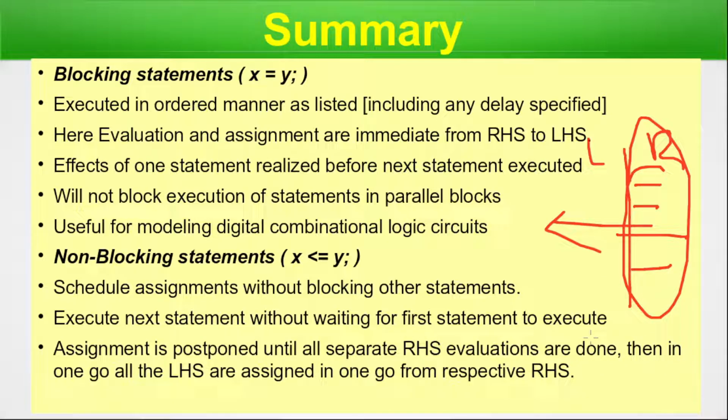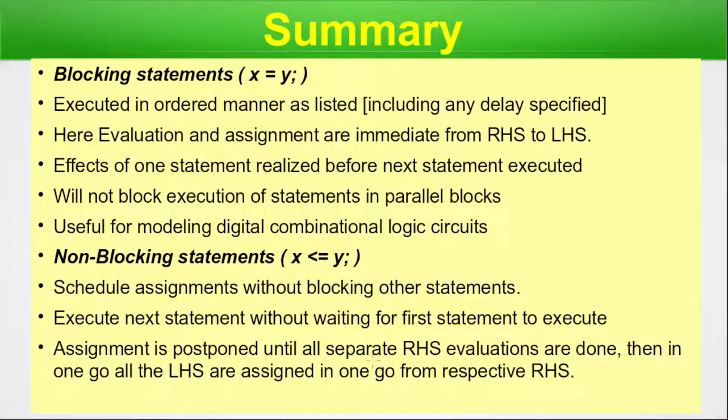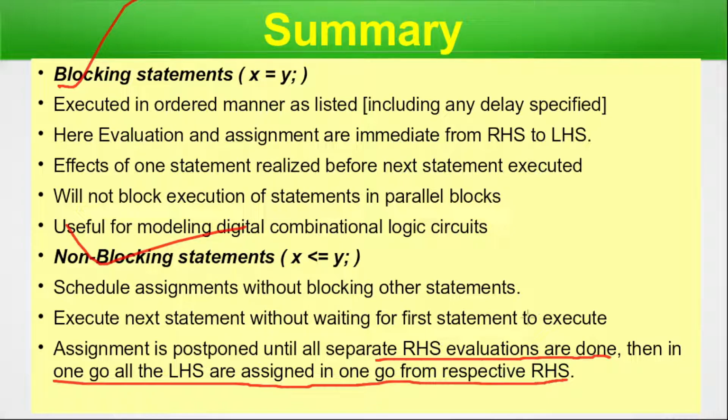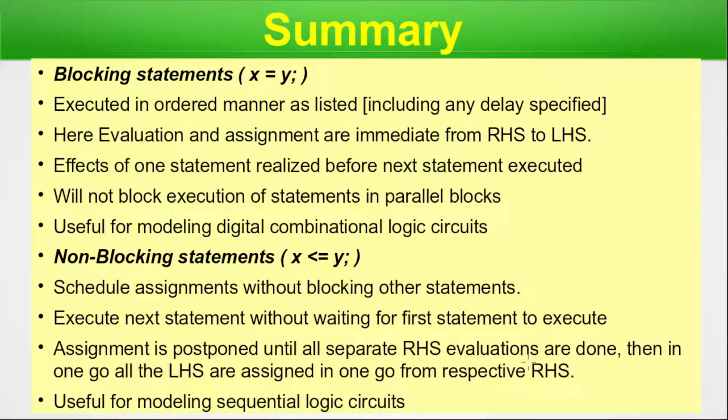Assignment is postponed until all separate RHS evaluations are done, then assigned in one go from the respective RHS. This is a very striking difference between the blocking and the non-blocking assignment. Useful for modeling sequential logic circuits.